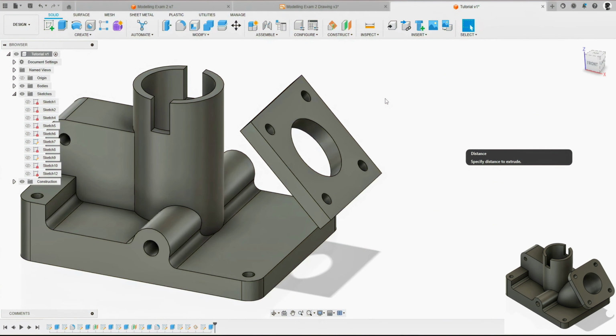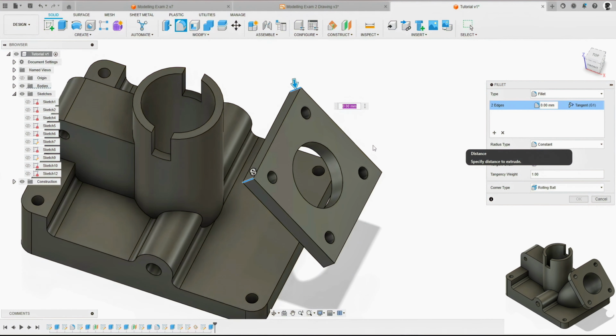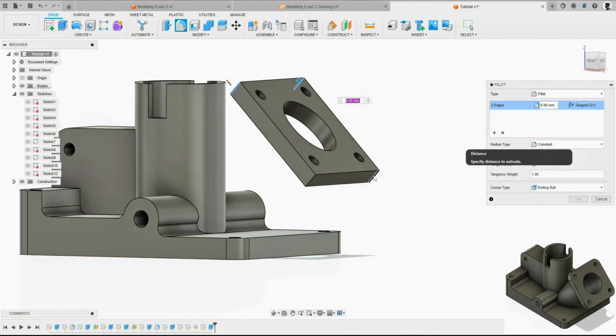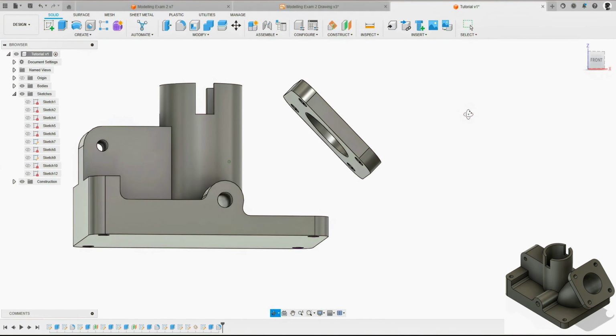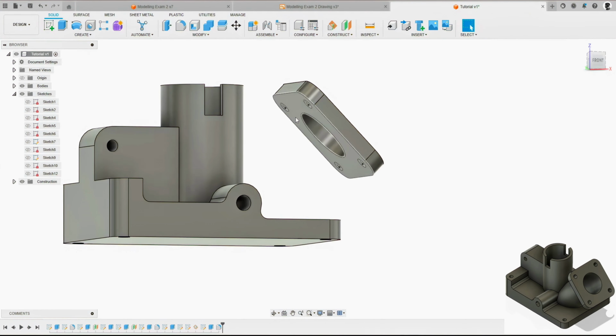Let's also go ahead and add in our fillets then. Let's press F on the keyboard, like 1 edge, 2, 3, if I can get that one, and 4. And I need to have a radius of 5 mil. Press enter. Looking nice so far. We just need to add in the last feature, which is the pipe section.